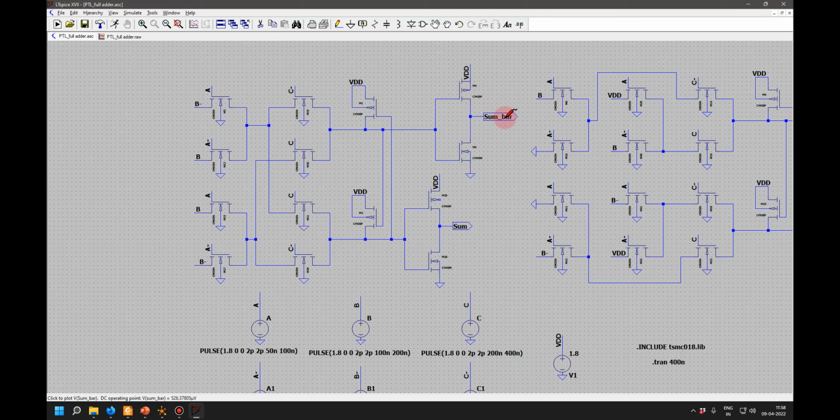Only the delays will change. Whereas if you remember when we learnt about the resistor NMOS topology or the depletion load, the output voltages VOL and VOH are a function of the width of the transistor. So we say it is ratioed. Is it okay?